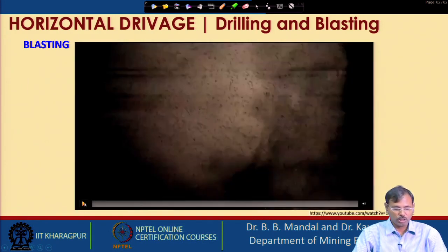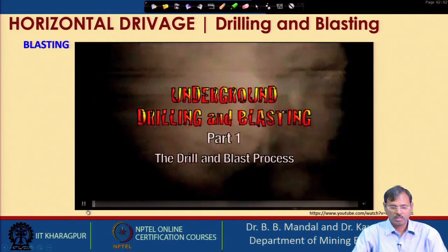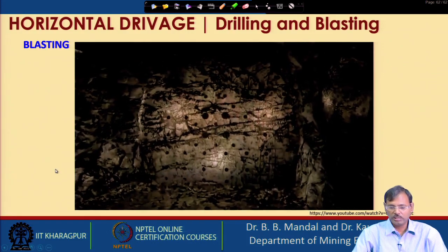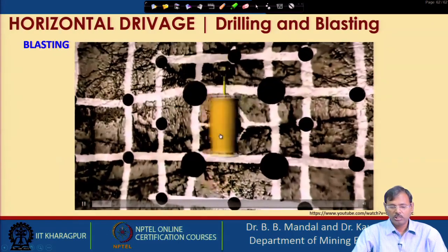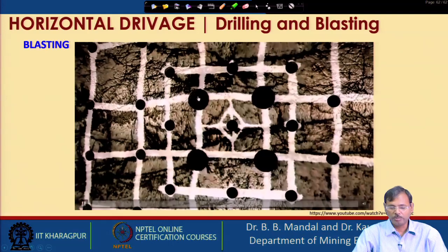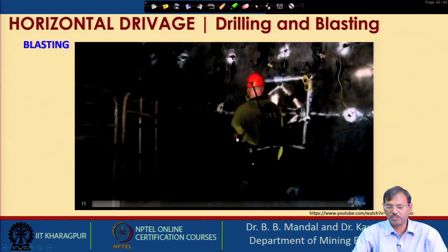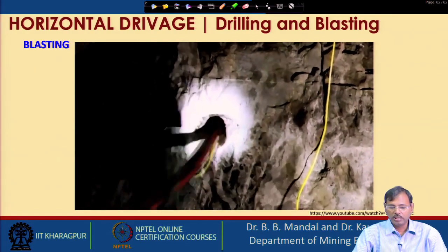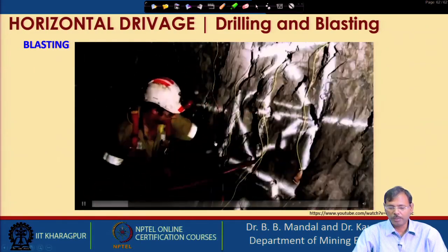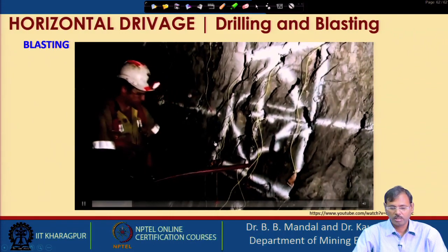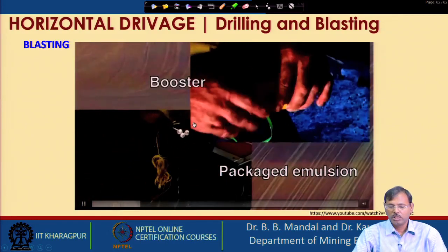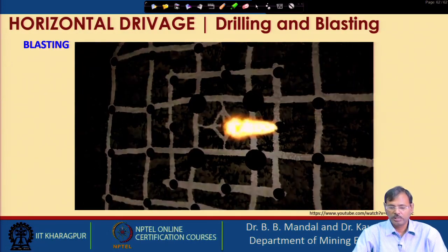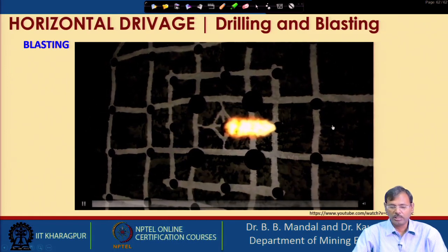So, this is one short video of the blasting. You can see this is an animated video. Consider these are the empty holes and these are the charged holes. Explosives are placed in the charged holes, empty holes are kept empty, and those will act as the free face for the nearest charged holes. Then the explosive is provided, you can see the pipe charges are provided here. Sometimes packed cartridges are also used, and the detonators are inserted, then it is blasted. In the animation you can see the blasting.